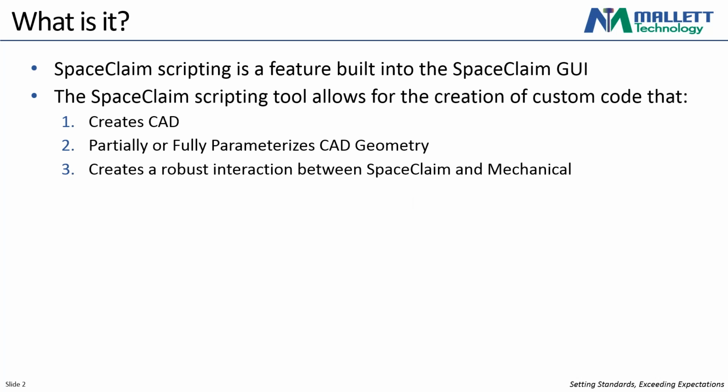I think about it similarly to the old ANSYS Mechanical APDL, if anyone has worked with it. As you generated CAD in ANSYS Mechanical APDL, it would generate a corresponding text file of all the various commands used to generate said CAD. I see SpaceClaim scripting as mildly similar to that. It's an avenue through which you can create and modify CAD, create name selections, and do any number of other operations to set up an analysis for parameterization and interfacing with Mechanical.